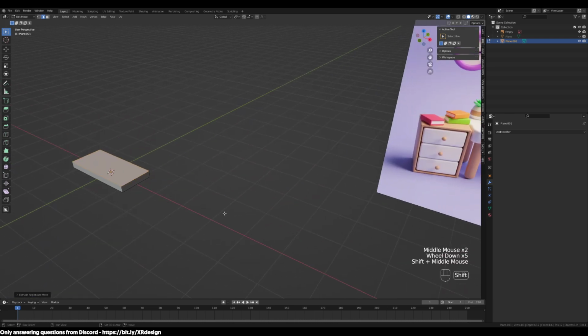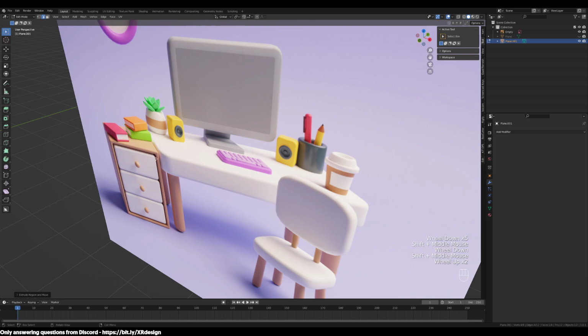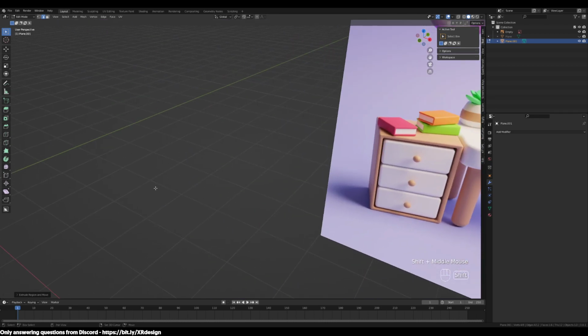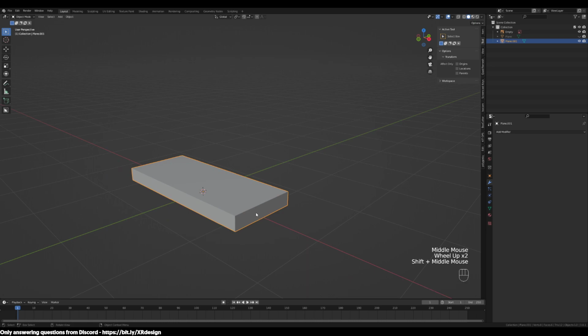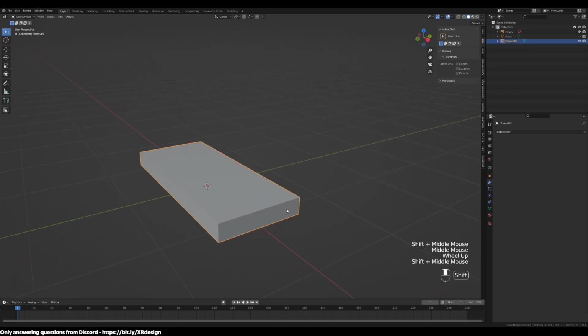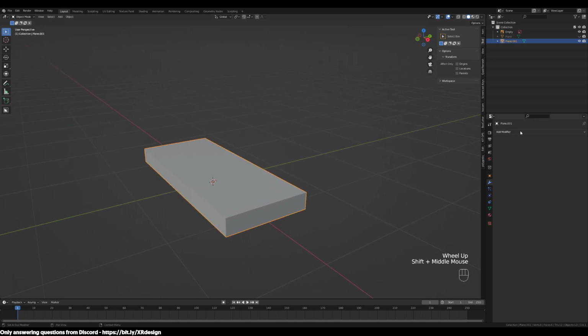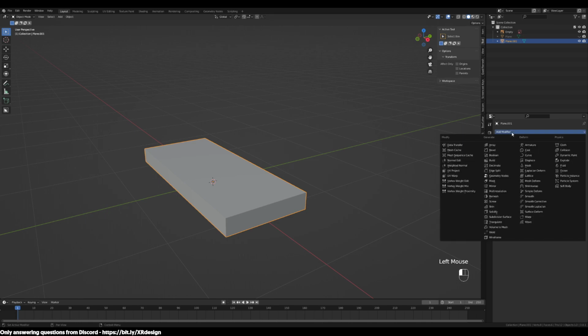And then as you'll notice in the image here, the 4 corners have a little bit more roundness than the top and bottom. There's two ways to go about rounding these corners, which is something that I wanted to touch upon in this render. But if you go to the modifiers panel here and hit add, there is a bevel modifier.